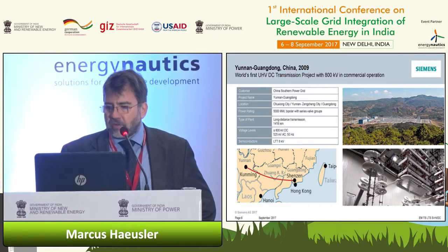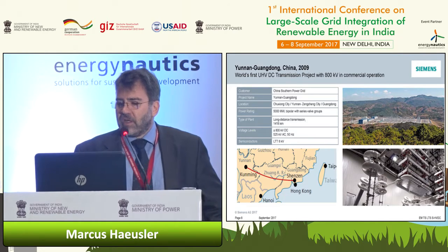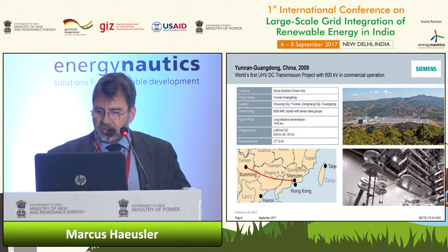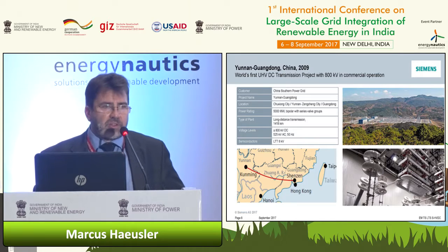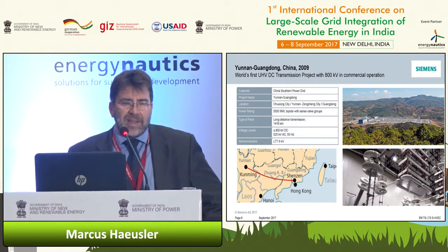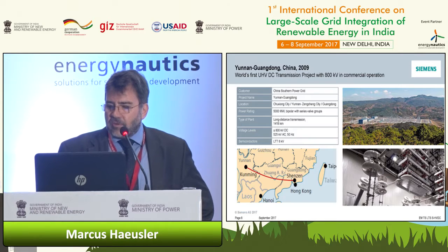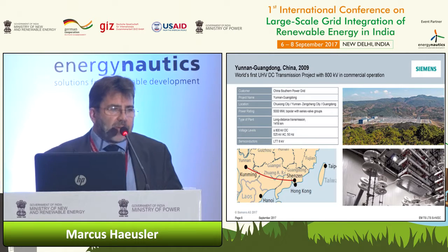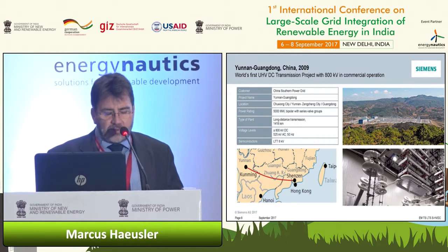You see here on the picture, unfortunately it's a little bit small on the top side, this is quite a large area such a converter station requires in the hilly mountain area. A large amount of this area is due to the number of AC filters and reactive power compensation equipment we need in order to compensate the operation of the converters. So that's one disadvantage or one requirement, that you need to have enough space if you choose such a topology.